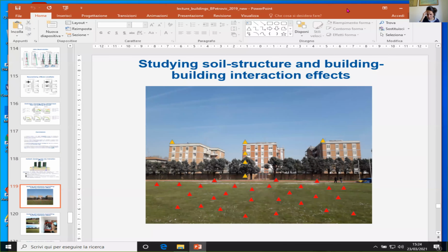Okay. I was wondering, in terms of the deconvolution operation, the part in which we also applied that operation to estimate the damping, the quality factor, whether or not the deconvolution introduced any type of artifacts in our signal that might be a problem or not to estimate accurate quality factors.